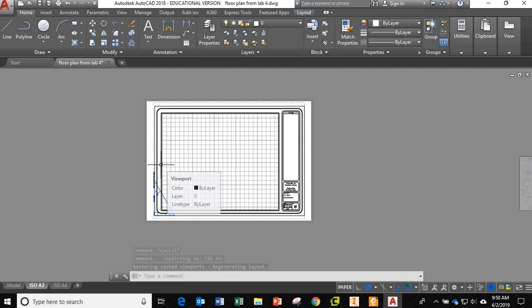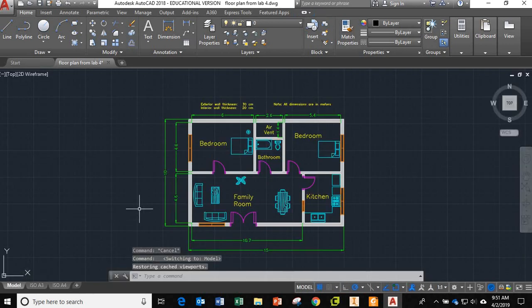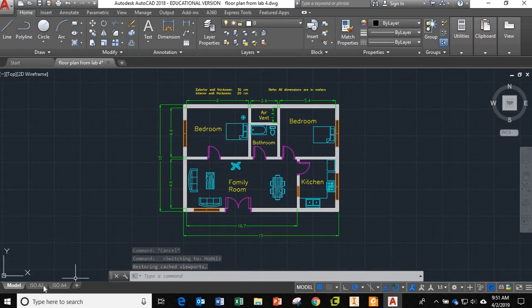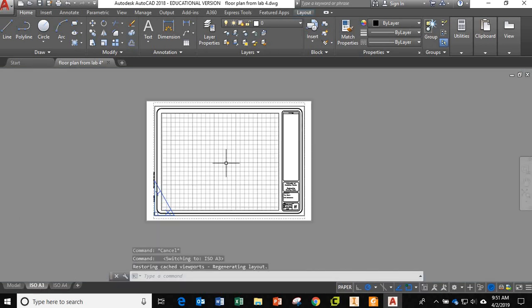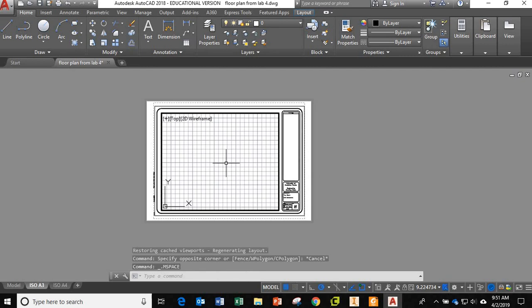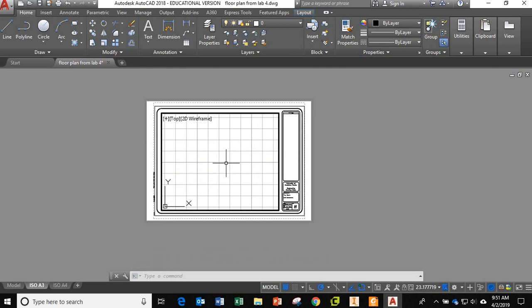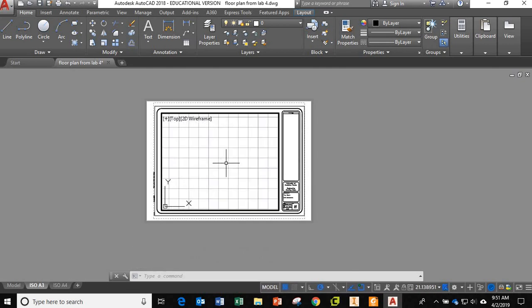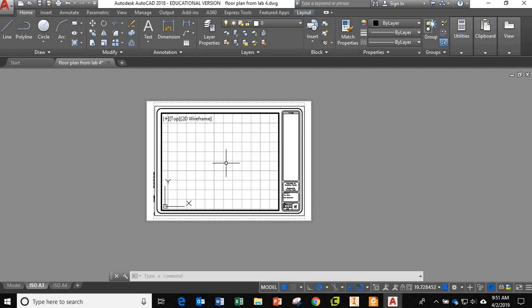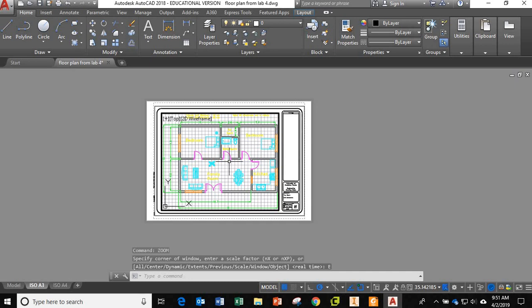And notice I've already drawn a viewport here for you. I showed in the last video how to create that, but that viewport is already there. So let's say I want to take this and plot it here. Let's double click on the viewport, and you say, well, where is it? You could start zooming in and out, but I don't see it. If it's lost somewhere, you can find it by typing in zoom here, pressing enter, and now you want to type in E or just click on extents, and now it will zoom in to wherever that is.